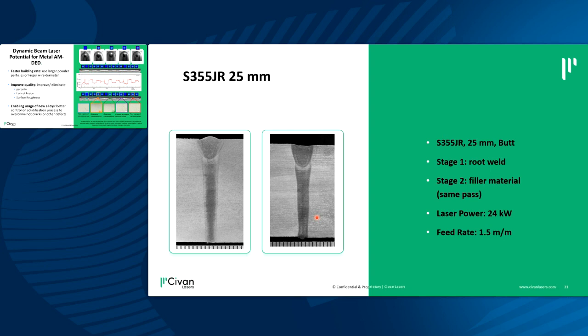What you see here is an average frame of a much larger video. If you look carefully, you can see that the geometry of the keyhole shown here is very similar to the beam shape you can see on top. This shows that we are really able to influence the geometry of the keyhole by using different beam shapes. Then here is a longitudinal cross-section of a hatch, and you can see that they have marked the beam shape used.